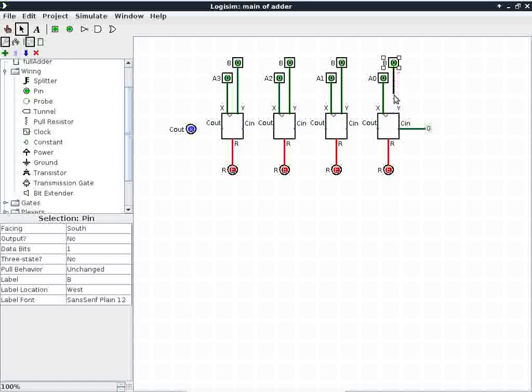In case you haven't noticed, I'm having a lot of fun here. All right, so we got, see, this one is all done. Input is 0, 0, and 0. The output is a 0. So the output of this one goes here, and you can see right away this one changes to a 0 too. And we are now propagating the 0 all the way through, and we're done with a 4-bit by 4-bit adder.